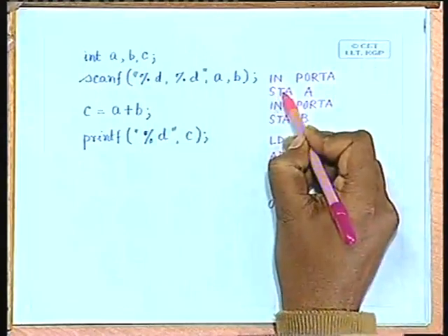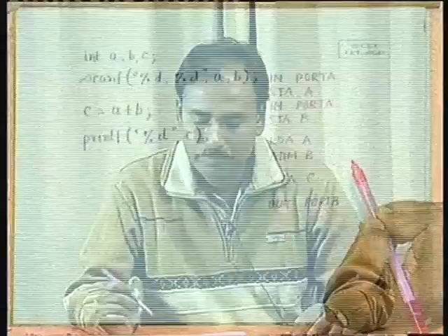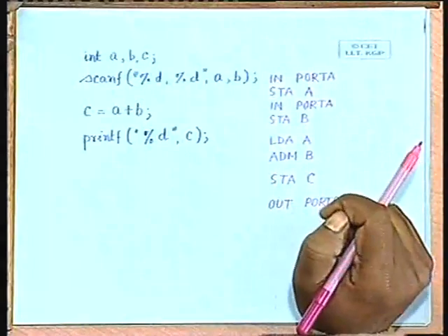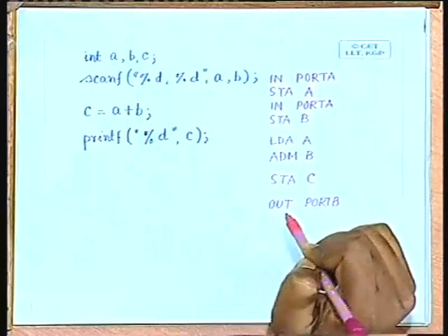Now, we had to perform this write back operation to the memory, because we have assumed that we have only a single register in the CPU till now. Now, let us see what advantage we will have if we have more than one register. So, in addition to the accumulator, if I assume that there is one more register, let us name that register as register R1.